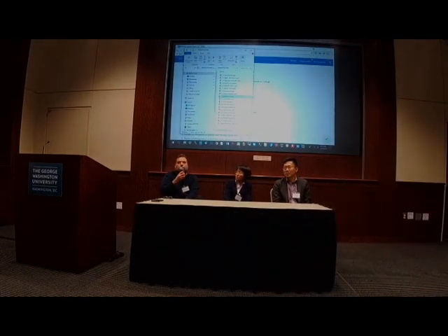Yes, and since the beginning of side channel research, 15, 20 years now, there have been proposals, and immediately we have seen side effects. One of the early proposals was dual-rail, for example, right? Using dual-rail encoding, where you encode a bit by putting data on two lines, and you say 1, 0 or 0, 1, right? And the first comment that came out, I remember, at CHES at the time, Adi Shamir raised his hand, spoke up and said, well, yeah, but you have a beautiful antenna there now. So the EM signature is improved, right?